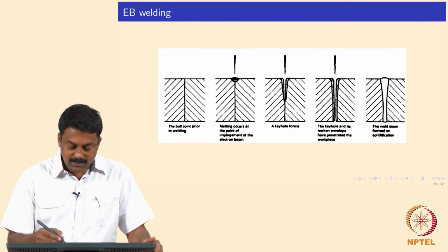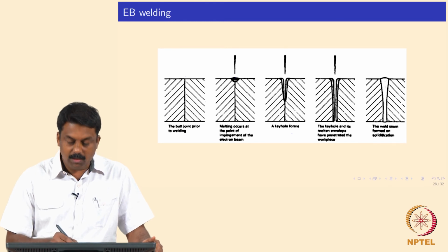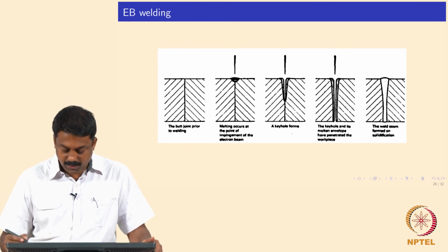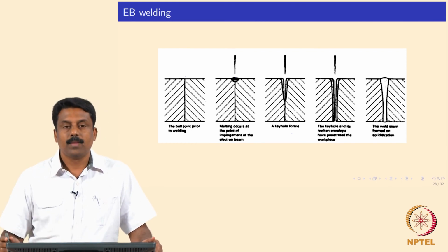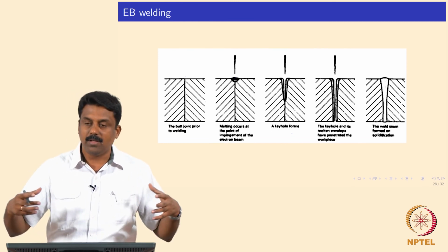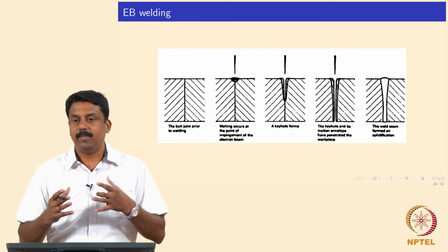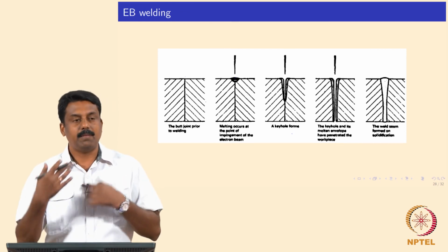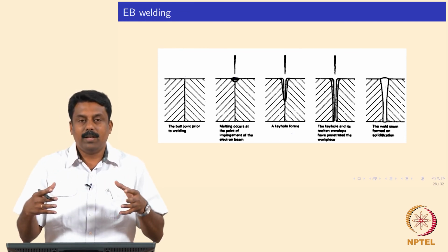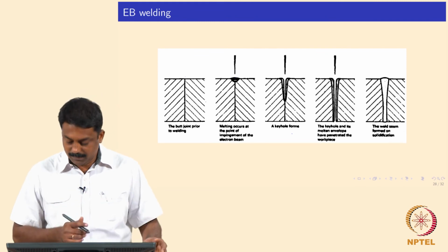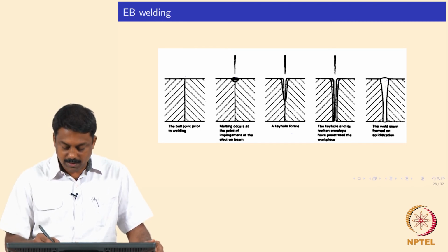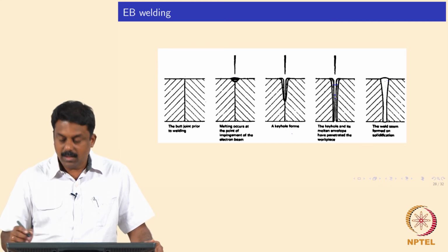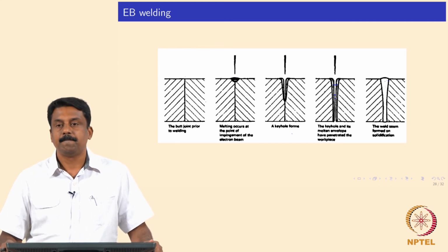and then you keep on focusing the beam. So, obviously the keyhole wall will be extended and you will have a full penetration keyhole, and the molten volume would encompass the keyhole, because the surface tension would never close the keyhole, because the keyhole formation forces like beam pressure, vapor pressure, recoil pressure are so high, your keyhole will never be closed. Okay. And then the moment the beam is off, obviously you will have solidification, and the surface tension would make the liquid interface coalesce, and ultimately it will solidify. Yes, it is clear.